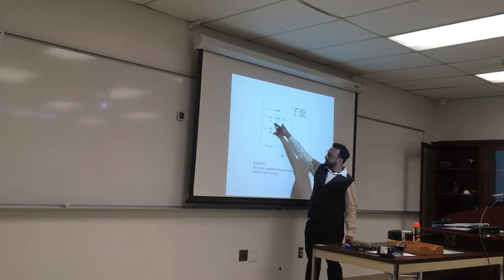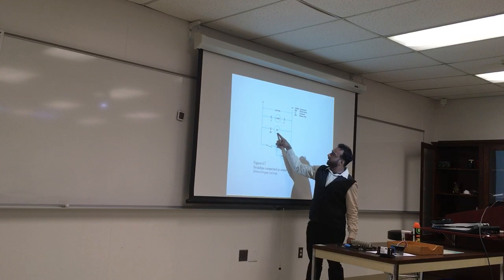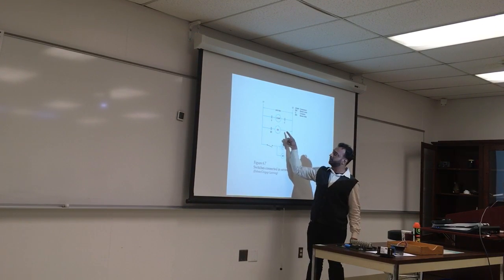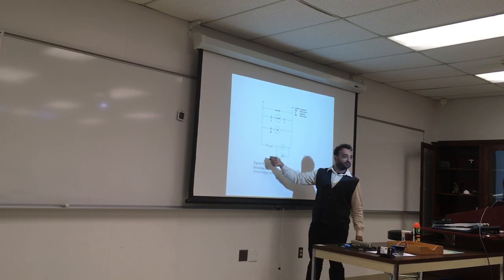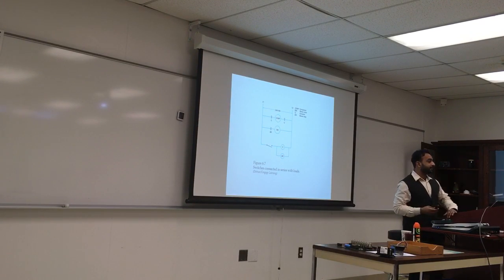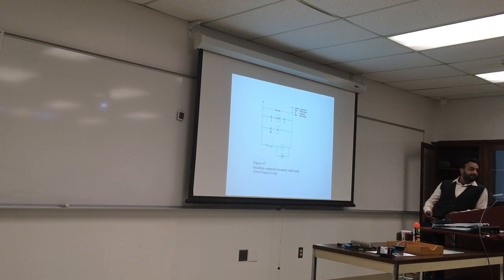The compressor needs some contacts. These are the contacts, and this is the control for the contact. And the blower motor is again simple AC with no thermostat. On and off: to turn it on, you turn on your compressor relay and the blower motor relay, and the thing turns on. This is very, very simple. No board, no thermostat, nothing. On or off. That looks very simple and easy to read.